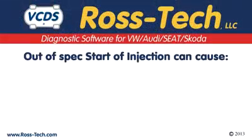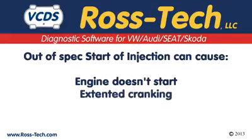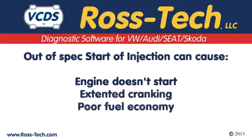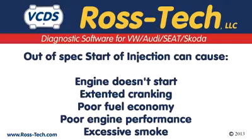If the start of injection is not set correctly, then there can be no start issues, extended cranking on cold start, reduction of fuel economy, poor engine performance, or excessive smoke while running.